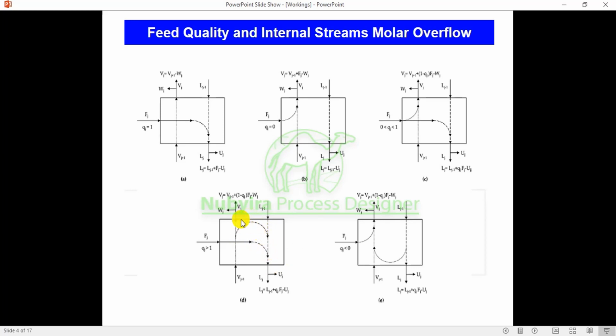some of the vapor that is coming, because the feed is having more cold energy, you understand? So some of the vapor that is coming from the stripping section will condense into liquids to that stripping section again, you understand? So it's going to take some of the vapor, and all the feed will also go to the liquid in the stripping section, you understand?